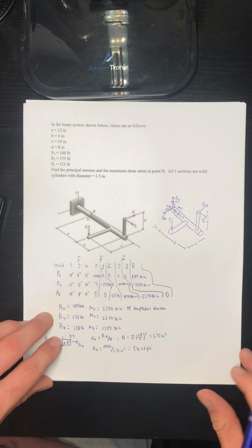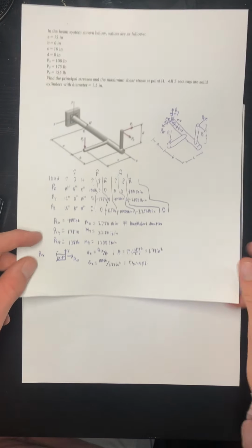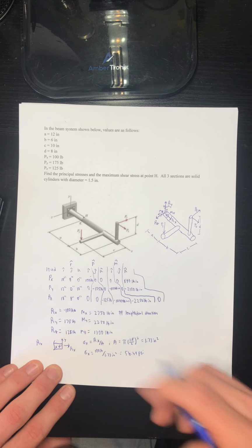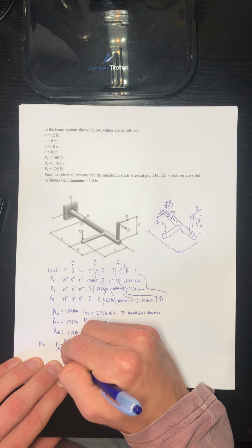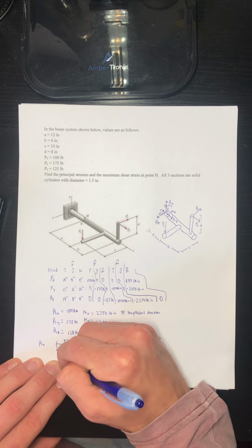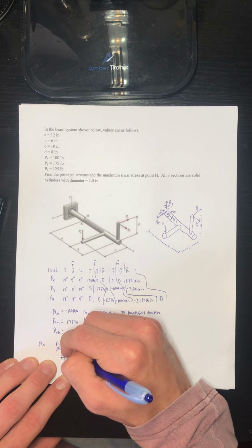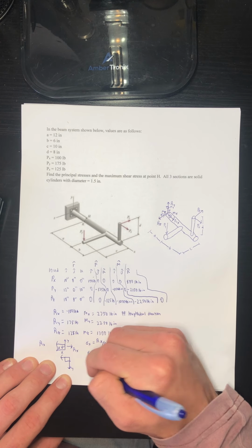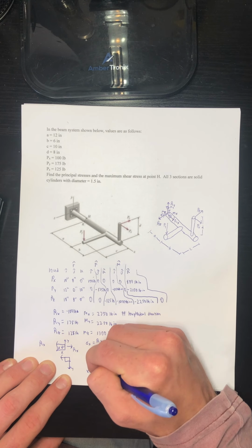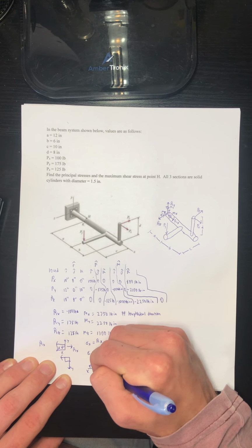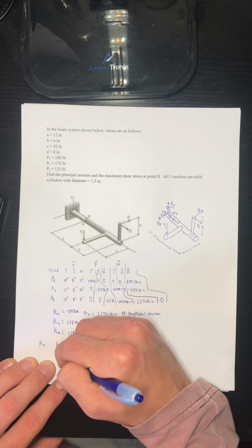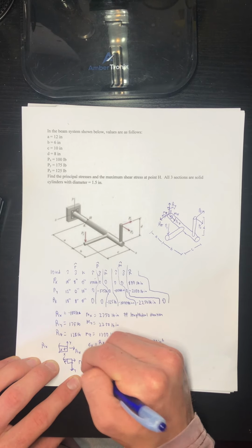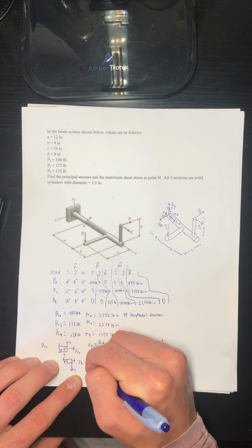All right, so we can go ahead and move on to our next force now. Actually, rather, I'm going to go ahead and put that on a stress block. It'll make things easier later on when we're doing it. So we have X, Y, and we have X, Z. And this tensile stress can be represented on these two blocks here.